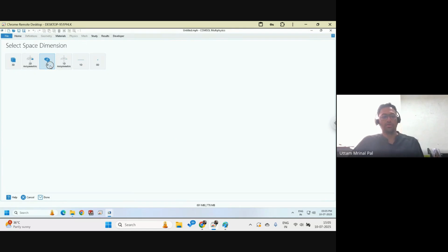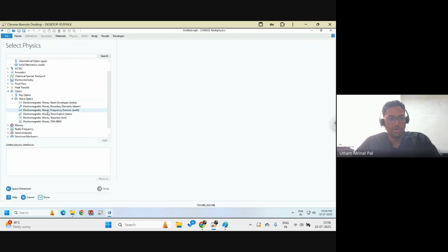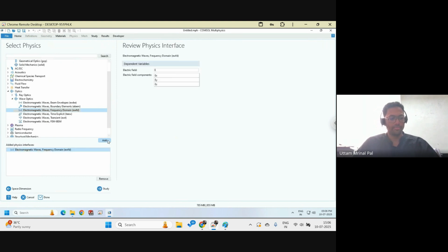Okay, and then we can go ahead and go to wave optics, and choose the same electromagnetic waves, frequency domain, and click on add. Okay, I'll wait for a few seconds for you guys to add this.